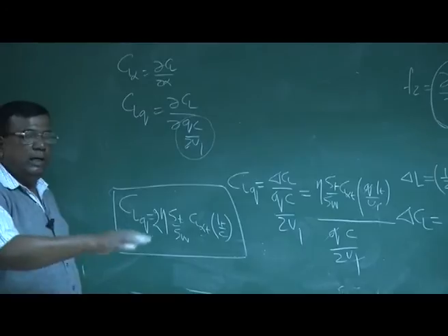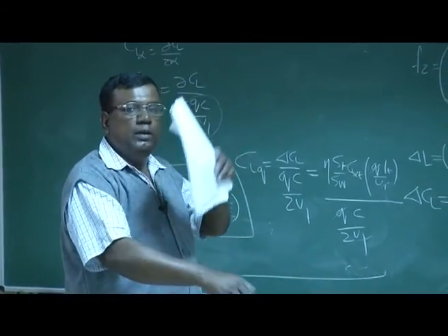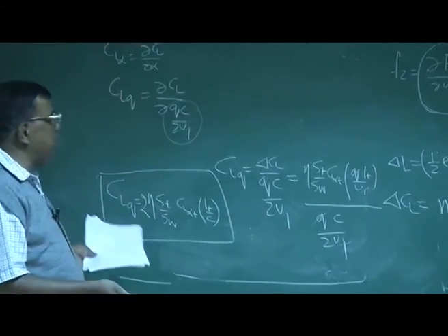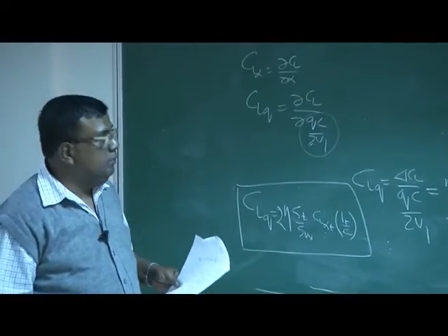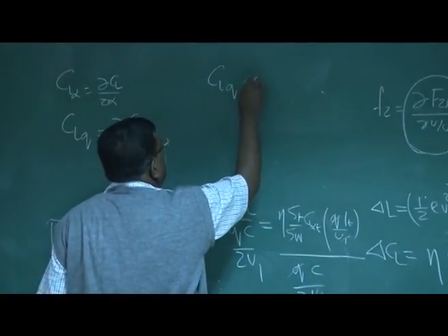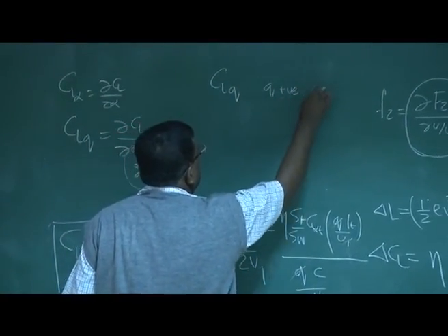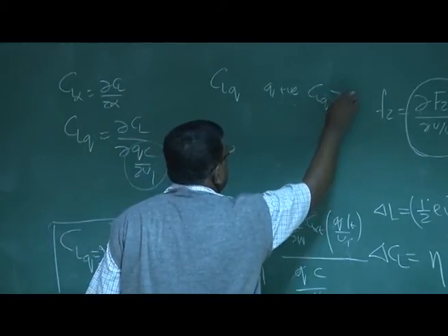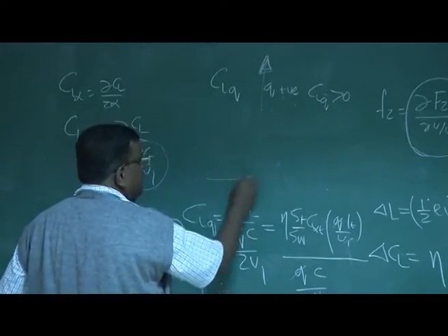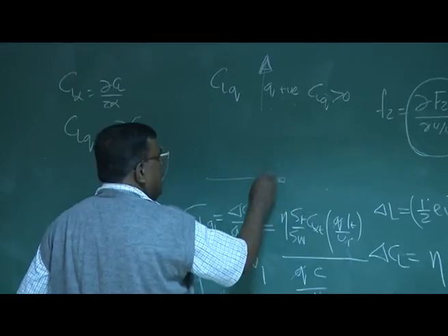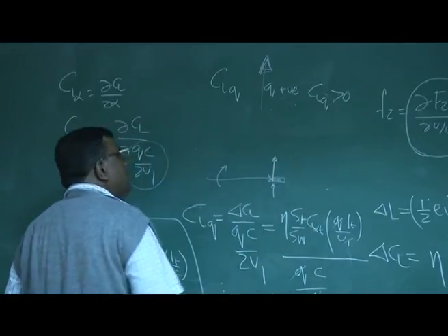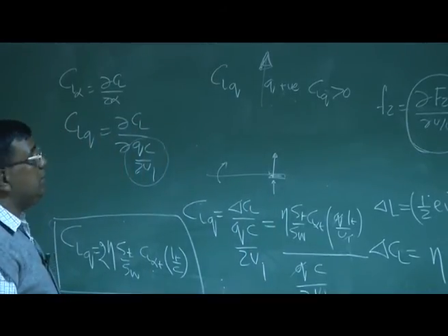Okay, so if the airplane is rotating like this, then the force will be in the upward direction, so it will be in the opposite of Z direction, right? Clear? If I want to use this expression in the Z direction, then it will be negative. That is how we write now the CLQ. If Q is positive, then CLQ, as far as sign we have seen, it is greater than 0, because this lift force will be upward, as it is going down. You will see that if this is the tail, as Q is positive like this, relative air is coming like this, angular momentum is increasing, the force is in the lift direction, but which is opposite to Z direction.